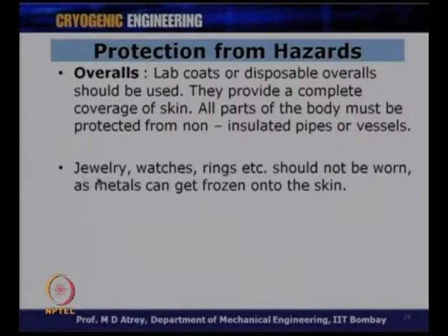Similarly, some precautions: jewelry, watches, rings, etc. should not be worn, as metals can get frozen onto the skin. Because of the ice that gets formed, your jewelry, watches, etc. can get bonded to your skin, and the skin can be peeled off if you want to remove these things. One should not wear such things while dealing with cryogens.